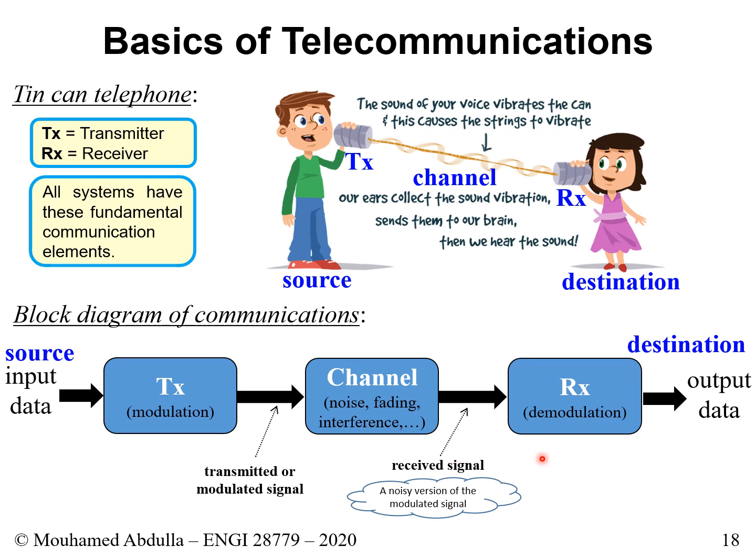Noise also exists, by the way, with wires. When you transmit a signal, and let's say you use an Ethernet cable, your signal will travel through the Ethernet cable, but then depending on the length of your cable, you will have a loss in the channel. You will lose some dBs because your cable, let's say, is too long. There's going to be losses, and there's going to be resistance in the wire, so you will lose power. So losses happen everywhere, mostly in a wireless channel, but even in wire channels, you will have losses.